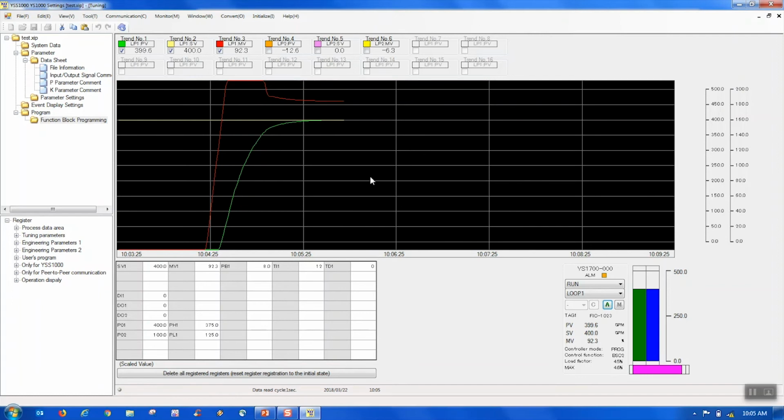And we're basically at a steady state here. The set point, the output, and the proportional, integral and derivative, our PID settings, come default in this table down here. I've also come in and put in some other values. I put in our DI that we set, DI1, our two DOs. DO1 was the high alarm or limit, and DO2 was the low alarm or limit.